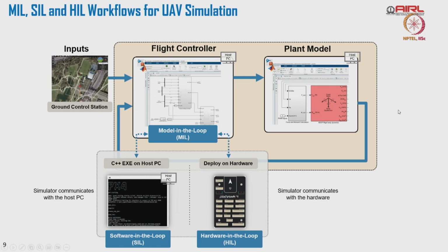Will they work in real time? Is there any problem when you are combining all the systems together, right? So there are some factors you need to take care of. How the simulator communicates with the hardware, that particular interface, right, is needed between the systems. And the data, when I am sending it out from my computer, the data received by the hardware, the data rate should match. There should be a proper handshake, right? You need to verify that.